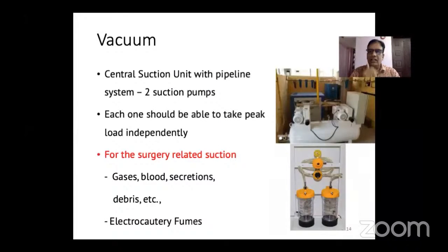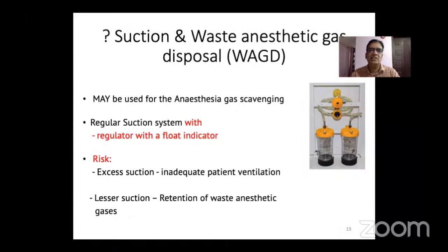And as part of the MGPS, or medical gas pipeline systems, we also talk about vacuum. If it's in a major setup, we should have 2 units. Each one should be able to perform independently, and the other will basically be a backup in the event of any emergency. Surgeons would use it for various purposes, and we also use it, for example, to suck out the throat or remove vomitus and other things in general.